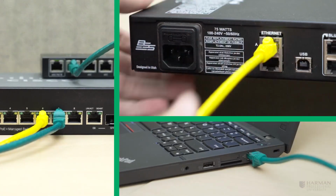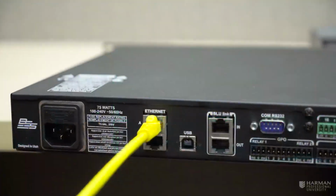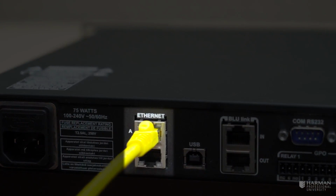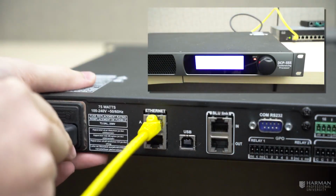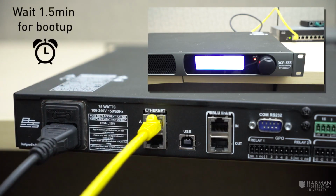Connect your computer and DCP-555 to the same network. Cat5e or better cable is recommended. Ethernet port A or B may be used to connect to the device, and in this demonstration, we are using port A. Connect power to the DCP-555 and wait about 1.5 minutes for it to fully boot up.